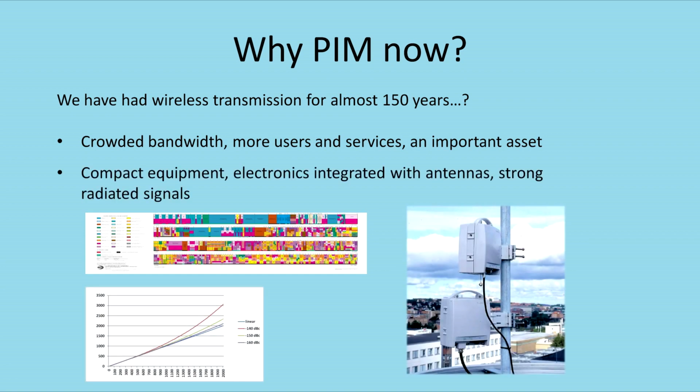Another factor aggravating the PIM problem is the practice of integrating the antenna, the electronics, and the cabinet of telecommunication devices. The more parts that are being exposed to strong electromagnetic fields close to the antenna, the stronger the currents and the greater the risk of PIM.